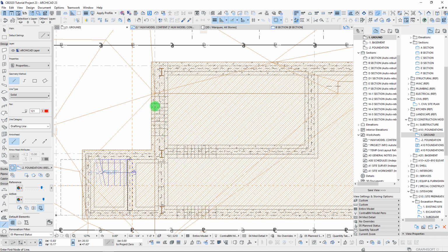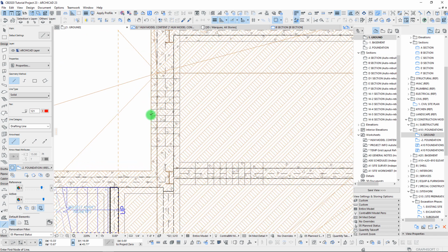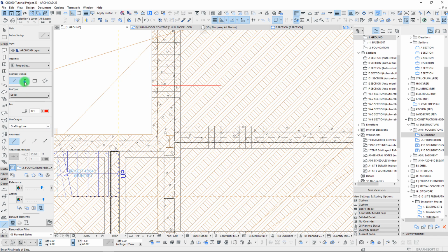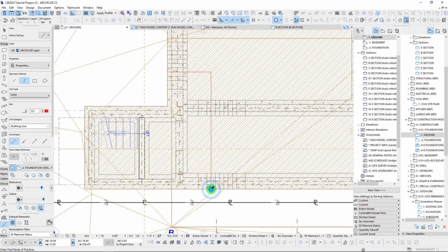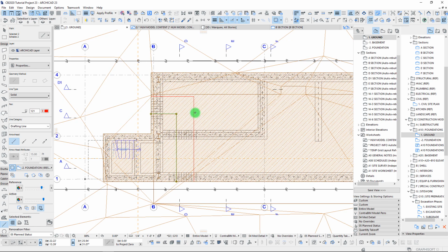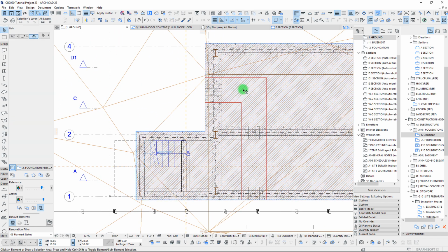and essentially what I'm looking for is I want this to be somewhere pretty much in like the back of these first few steps. So we're going to go, I think probably we'll go to the second step, and we'll hope that this picks it up right for us. We can always adjust these as needed. So right now we are just creating some lines that we will use as kind of like a point of interest. And so I'm going to offset this, and we'll offset 3.5 feet here. So, okay, so that's part of it here.